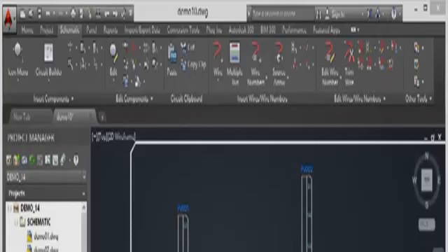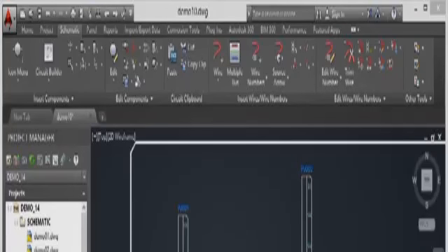Now, what's this hold option? What does that do? Well, let's go through that one more time, but this time we'll use the right click on the mouse. So I'll select the component again, right click, rotate connector. And then I've got this hold option. So if I right click again and select hold, it says hold attributes at original orientation, yes or no. If I say yes to that, and then select the connector to rotate, it holds them in the original position each time I click.